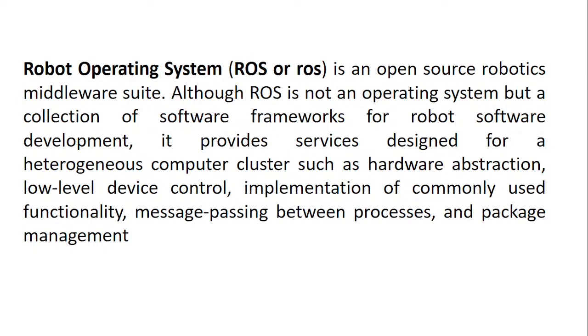You can also integrate lower level hardware like small microcontroller boards, whether it is Arduino or ARM or PIC or any other microcontroller board, into that same system. So all these hardwares are different types of things, and then we can have a LiDAR sensor, 3D cameras, 2D cameras, GPS, and other odometry sensors, and wheel odometry data.